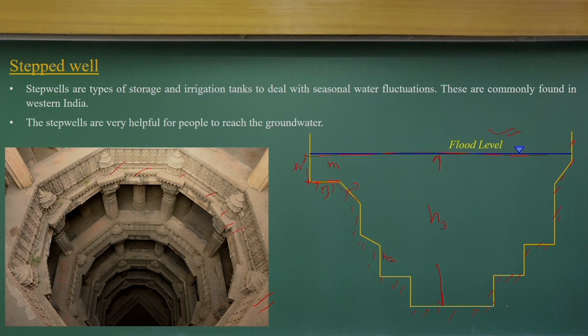For a horizontal surface like here, it is very easy. If I have the fluid rho 1 and the height is h3, the pressure at this point is P atmosphere. You know it, the pressure at this point will be P atmosphere plus rho g H3. And the pressure distribution will be uniform as it is a horizontal surface.